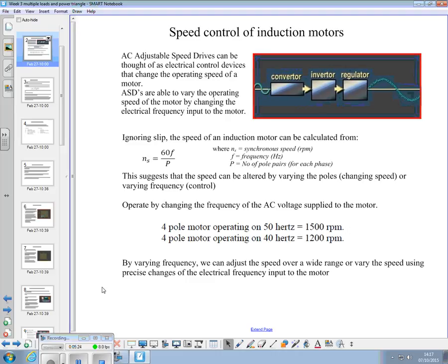So, these adjustable speed drives, what they do is they take the AC sine wave, and the simplest way to describe what an inverter does is it takes the AC mains, either 400 three-phase or single phase, and that's another thing. You can run a three-phase motor on a 240 volt outlet with an inverter, because that inverter is creating the three-phase rotational magnetic field that you need.